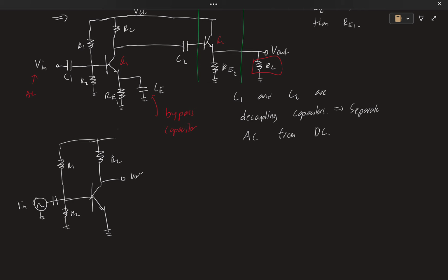First things first, this is going to be VCC. Before we can apply any small signal model, we want VB. Maybe the module wants a gain of 20, I could be wrong, maybe 50. Before we can even talk about what gains we need, we need to determine what region we have to operate in.